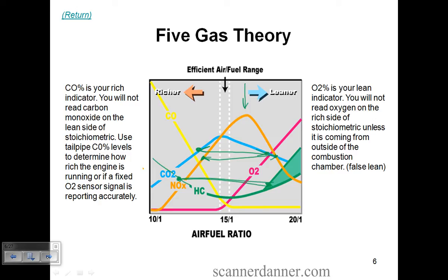If I look at the CO measurement, can I tell which side of stoichiometric I'm on? Absolutely. If I see any CO at all, which side of stoich am I on? Rich. What is CO? CO is gas burned without enough oxygen. It's carbon monoxide.